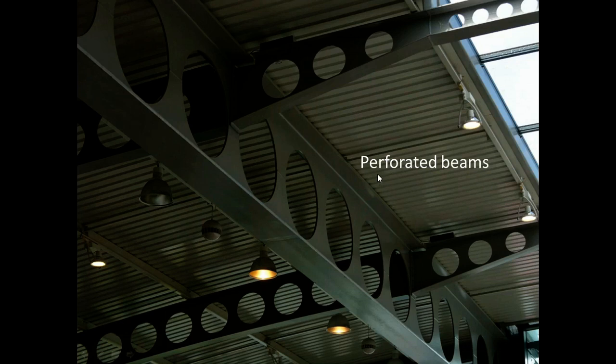And a more advanced version of this is the perforated beam. As you can see here, we've now got large holes perforated into the beam. You can almost imagine, you can just about see that it's almost becoming a truss, if you remember early on. So it's a flange up here, a flange up here. The web, the two flanges are kept apart. You could imagine a horizontal section, vertical low points here, vertical rods, and a little bit of triangulation here to help stabilize the whole structure itself. Okay.